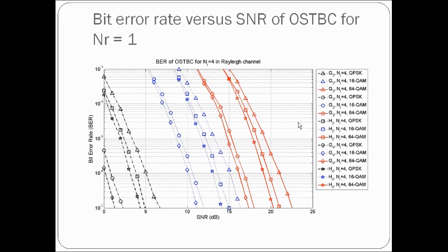This figure shows the results for the case when NR equals 4. For a particular modulation parameter value, it can be observed that the performance varies in the order of G4, G3, H4, H3 and G2. It was noted that a similar pattern is found at low SNR when NR equals 1, where G3 is greater than H4, which is greater than H3, despite the latter having higher gain.